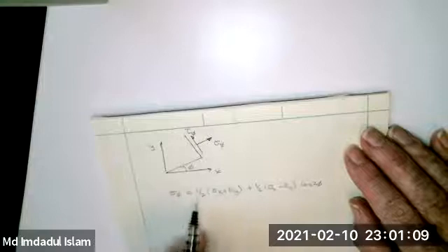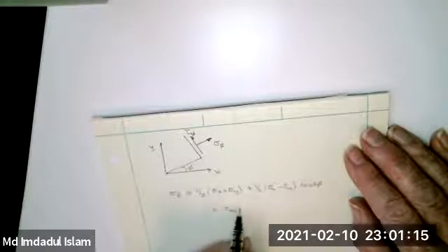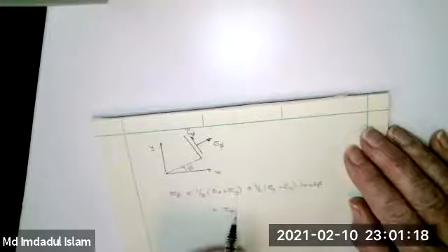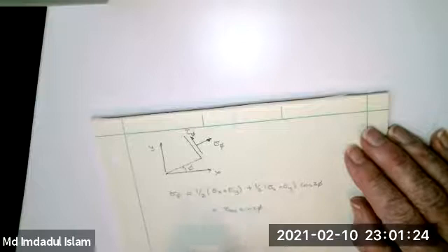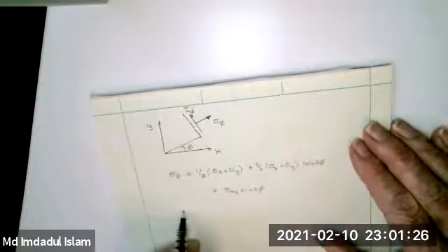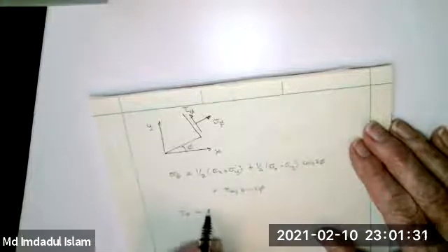And the shear stress in XY coordinates will all be converted to normal stress when you get to a principal stress. So tau phi would be 0 there. But this is for any general plane, so tau phi is not in general 0. If you make it 0, you get principal stresses.